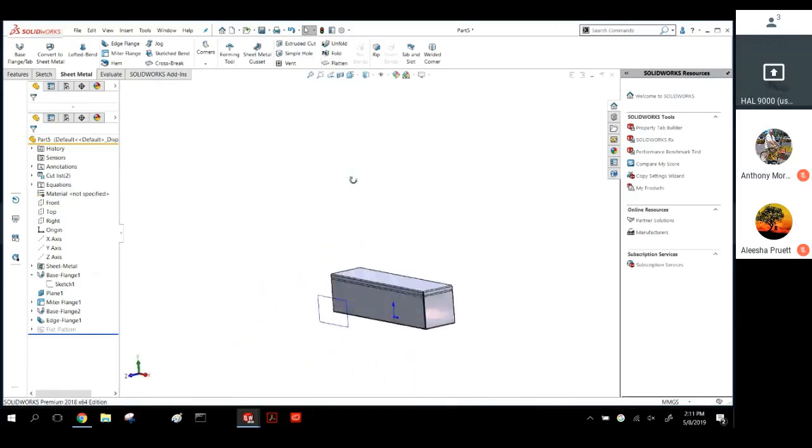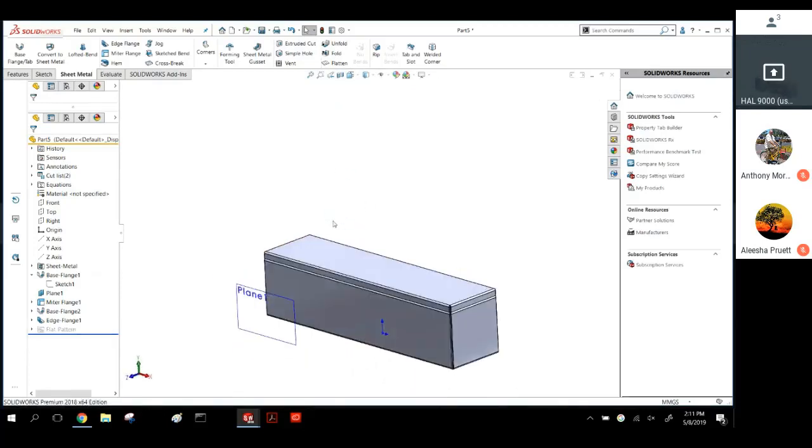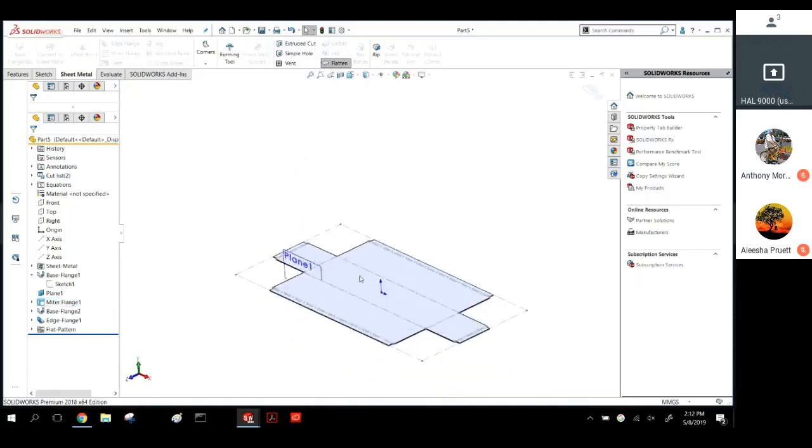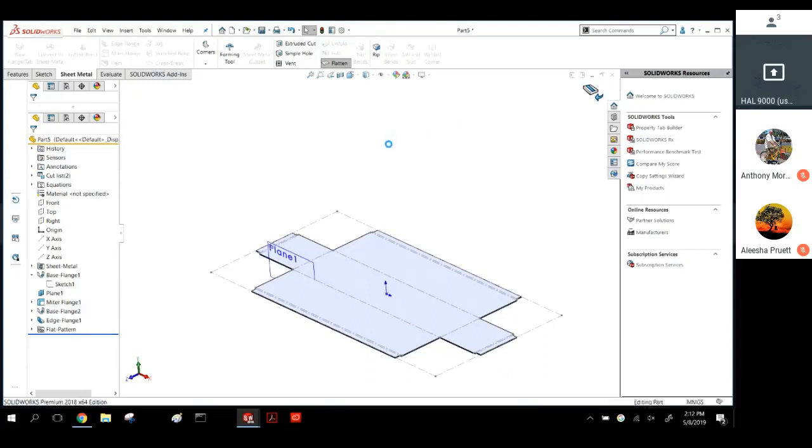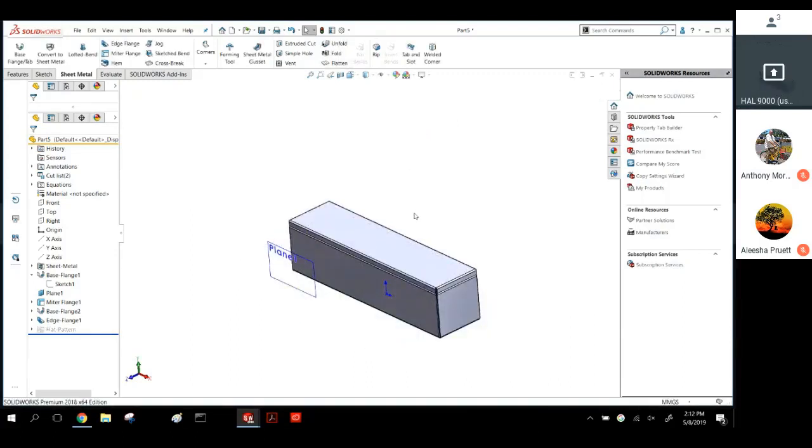That's typically how I'll do enclosures, is using either one of those tools. If it's just got a regular top, that's fine. But if it's got something a little more fancy, I'll usually use that miter tool. Get myself a pretty complex box really fast.